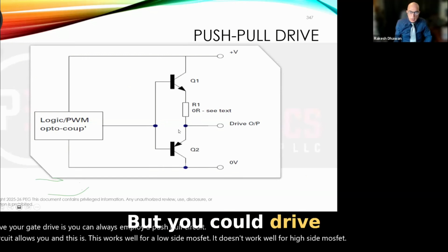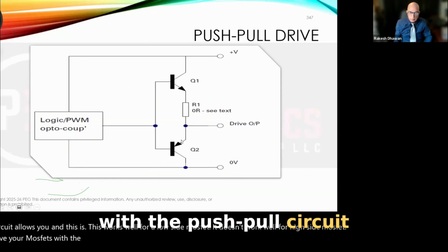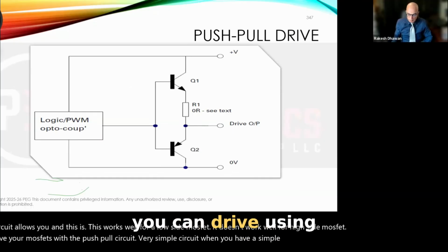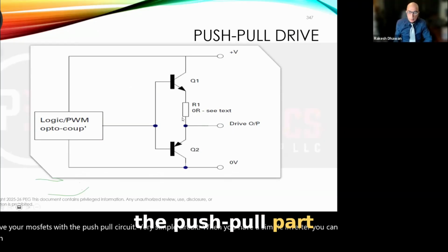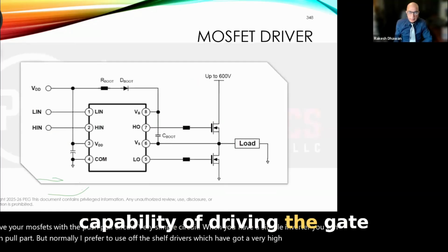But you could drive your MOSFETs with the push-pull circuit. Okay, very simple circuit. When you have a simple inverter, you can drive using a push-pull part. But normally, I prefer to use off-the-shelf drivers, which have a very high amp capability of driving the gate.